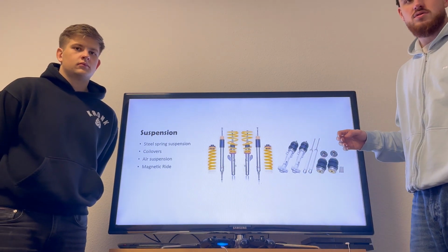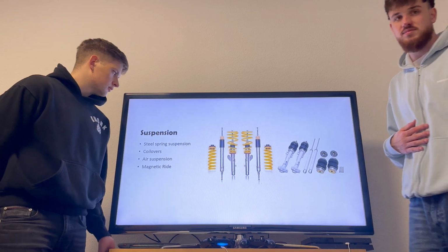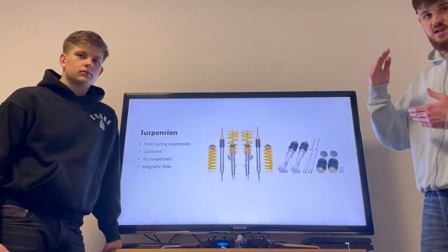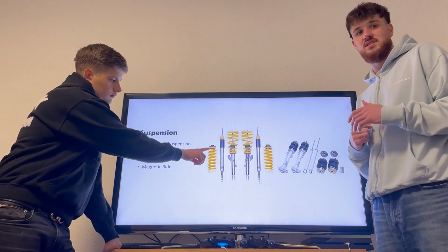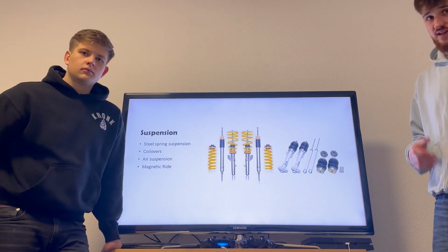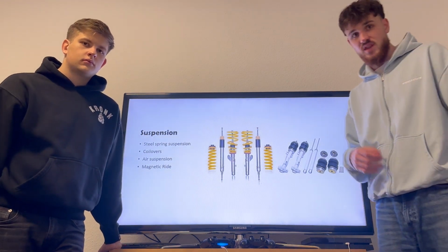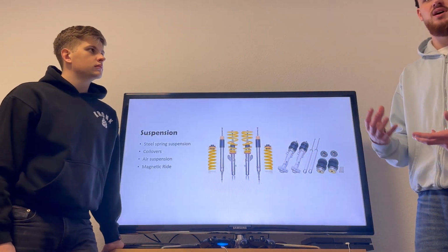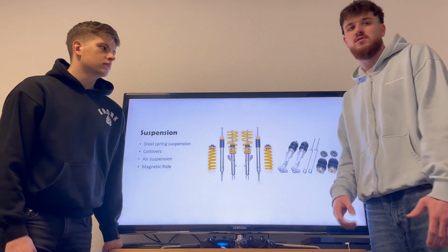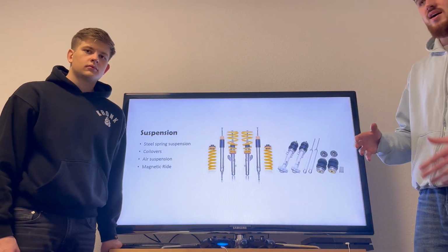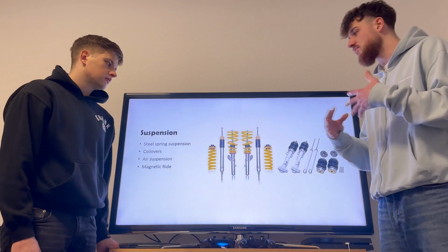So next we go on to the springs. The springs absorb the shocks and start to oscillate, and the damper has the task to eliminate the oscillation as fast as possible. Mainly for driving aspects, but also for comfort. So that the car has all four wheels on the ground in every situation.